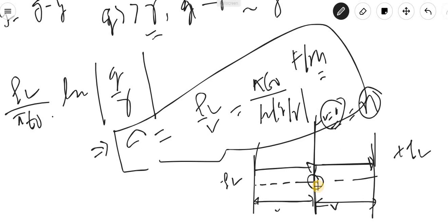This means the capacitance of one conductor with respect to the neutral plane, the conducting plane considered as a neutral plane, is 2 times the capacitance of the single phase line. That means simply it is presenting the series combination.